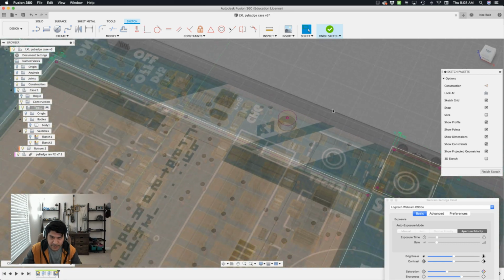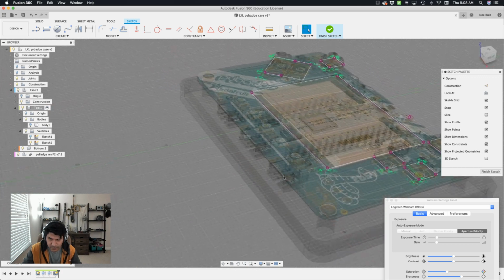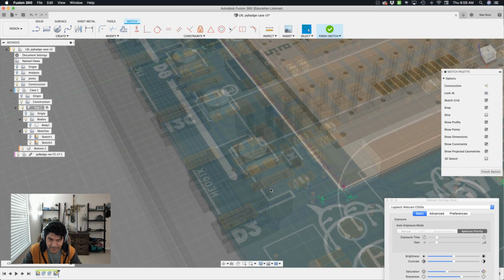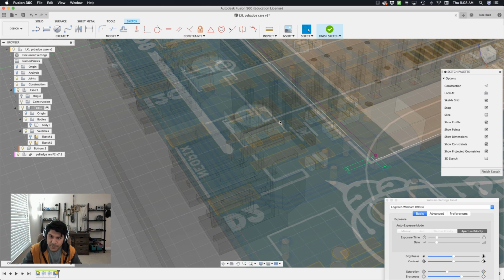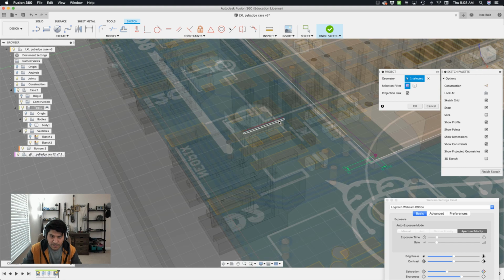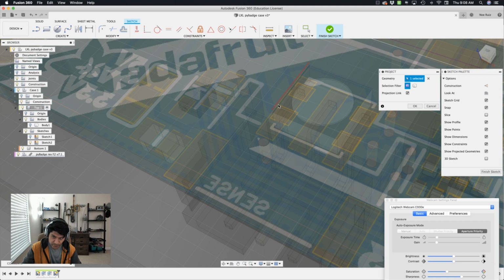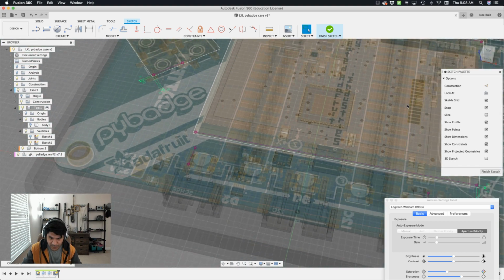All right. Is there any other? Yes, the other components that we need to work with are the neopixels. So let me get in here and get a look at the pixels. It's a little difficult to see because it's in this ghosted mode, but that's fine. I want to project in this edge, which is the last pixel going to the right side. So project this edge, and then the opposite pixel over here further to the left, we're projecting that edge. Sweet. So now I have those.